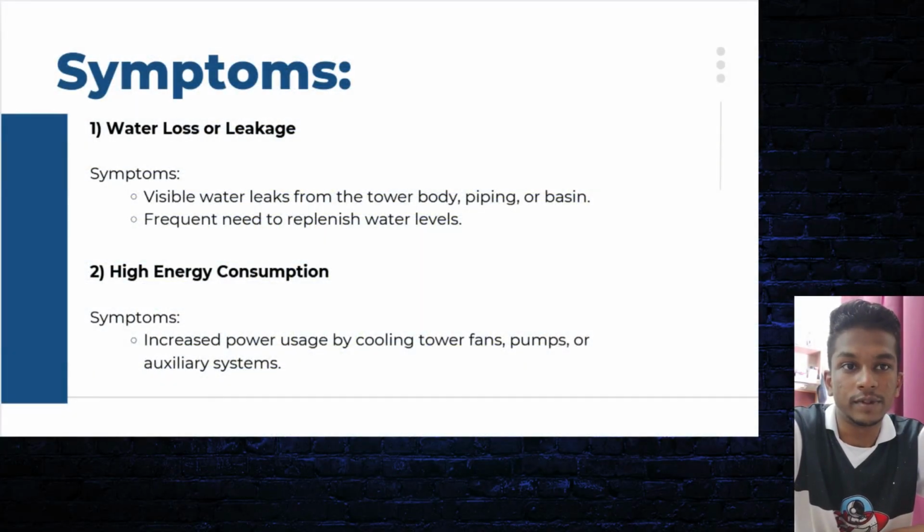Next, for the symptoms, the first symptom we will see is water loss or leakage, which we can see by visible water leaks from the tower body, piping or basin, and the frequent need to replenish water levels.